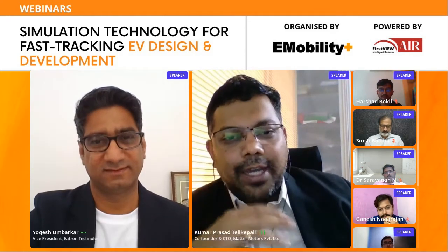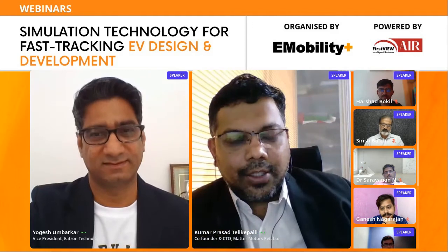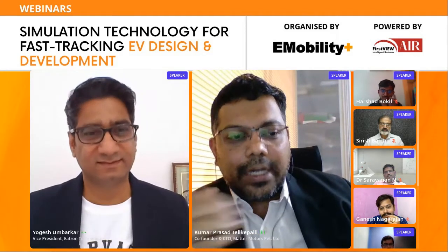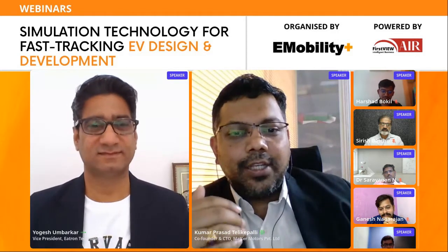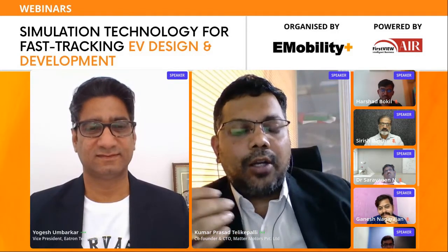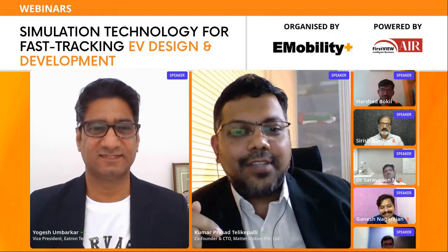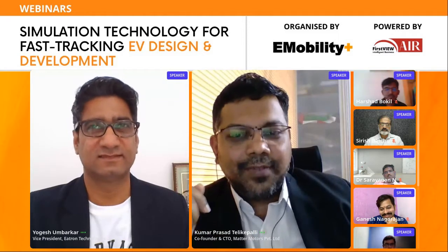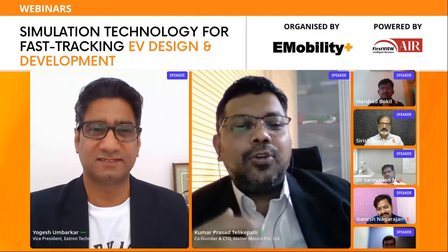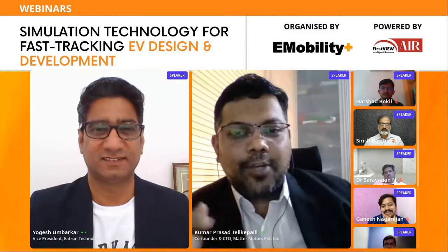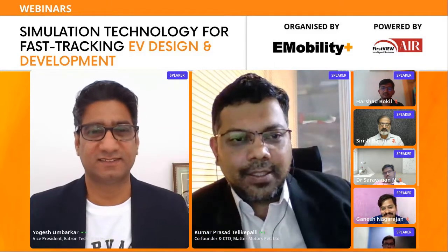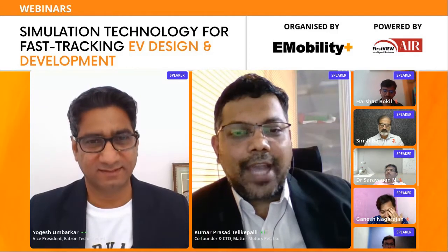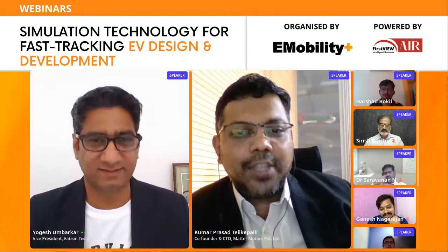Now, when you get to a high speed electric machine, especially with permanent magnets, you are actually using a d-axis component of your current, which is demagnetizing the flux all the time to achieve these high speeds. What many people relate to as performance loss and attribute only to the battery packs also comes back to a thermal effect on magnets actually losing their remanence flux.